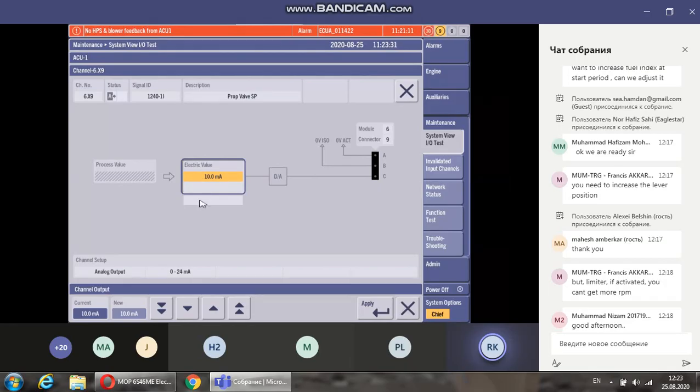So it is from the connection in the multipurpose controller cabinet further down the line that you'll have to check if you have any issues. Okay, so you can swing through all the way to whatever you want, as long as you are within the 0 to 24 milliamp range.